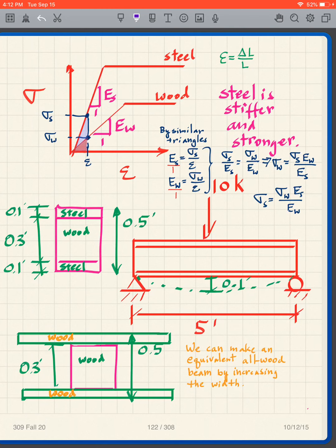Now what happens when we bend our beam, we talked about it. When we bend the beam, let's just say we're bending it like this, what happens? The bottom fibers are getting longer. If the bottom fibers are getting longer, that means I have a positive change in length. And remember what the definition of strain is. This is normal strain, epsilon rather, don't call that E.